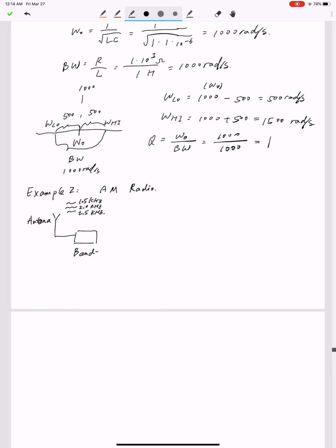a bandpass filter. The bandpass filter actually is the frequency selector. And after the signal goes through the bandpass filter, the next module is a signal processing module, which will further reduce the noise from the signal you picked.